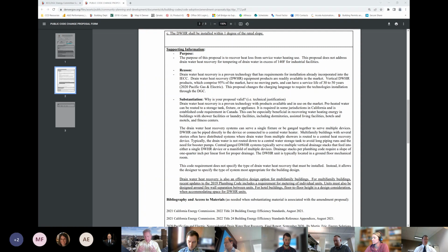What gets really tough and cost inefficient is when you're adding a bunch of pipe just to get a recirc line back through, and recirc's the wrong pipe, by the way, because you're usually keeping your recirc at like 110 degrees or so. It's just water that's not being used by the fixture. So if you were to take that back through the drain heat exchanger, you'd end up heating your drain line. You don't want to do that. The only way these things work is to take cold water through the drain line and then take it into what would have been cold makeup to something like a domestic shower valve. Another place it can go is a small little water heater within, again, 10 or 15 feet. But you start going much more, 20, 30, 100 feet, and you're buying a lot of copper.